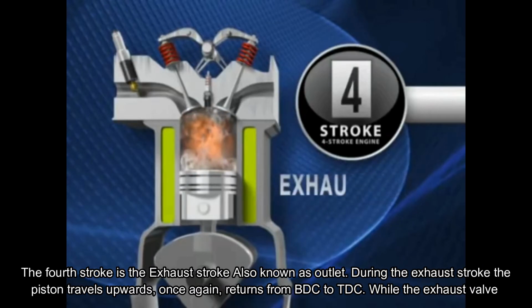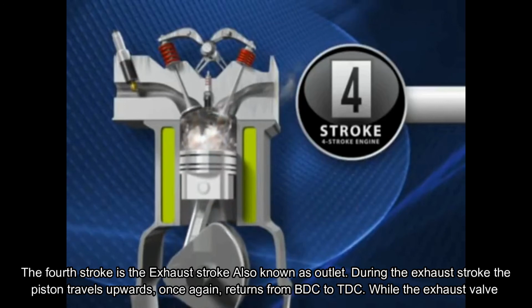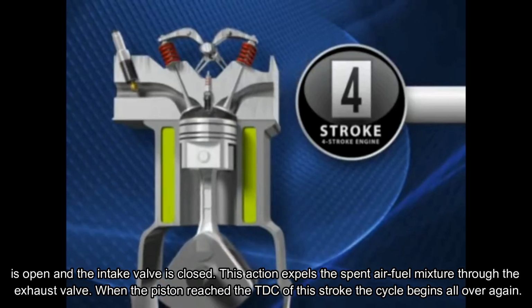The fourth stroke is the exhaust stroke, also known as outlet. During the exhaust stroke the piston travels upwards, once again returning from BDC to TDC, while the exhaust valve is open and the intake valve is closed. This action expels the spent air-fuel mixture through the exhaust valve. When the piston reaches the TDC of the stroke, the cycle begins all over again.